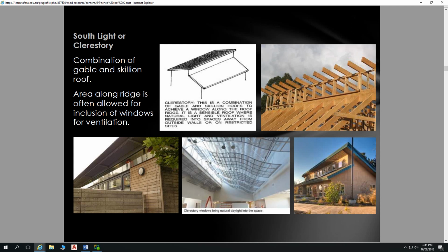But in residential architecture, it works well, like we have in this bottom right-hand picture here, showing those windows facing north with an adequate overhang over the top to allow sunlight to pour in to the back of the building in wintertime, but then in summertime, when the sun is directly overhead, those windows are adequately shaded. So such a construction allows you to have well-lit rooms to the northern side of the building, but also well-lit rooms to the southern side. It enables that penetration of light from the northern side in wintertime throughout the building.